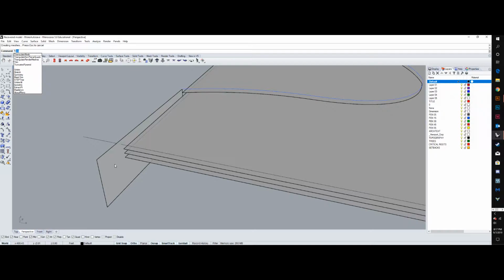This is a little weird dance I'm making here to make this endpoint really quickly. I extruded this curve out. I'm going to hit trim. If I spell it correctly, trim, enter, select my plane, enter, and then trim off that line. Now I'm going to delete this plane because I don't need it, and I'm going to delete the line that I don't need.